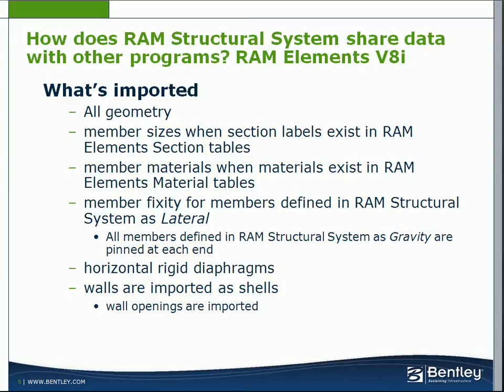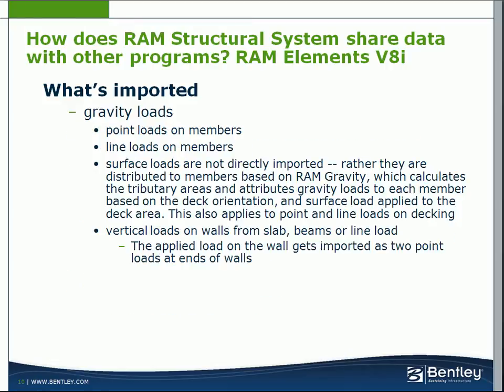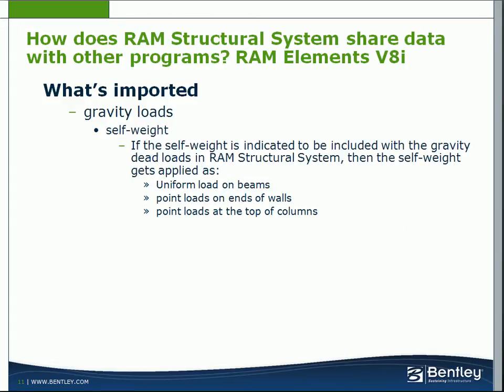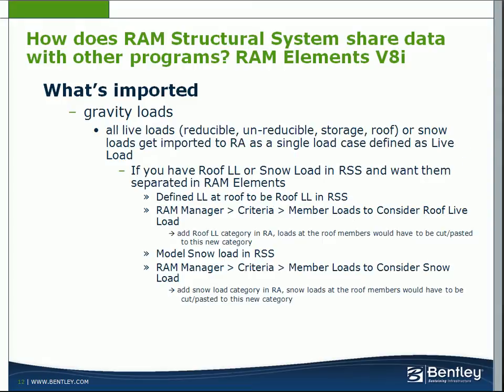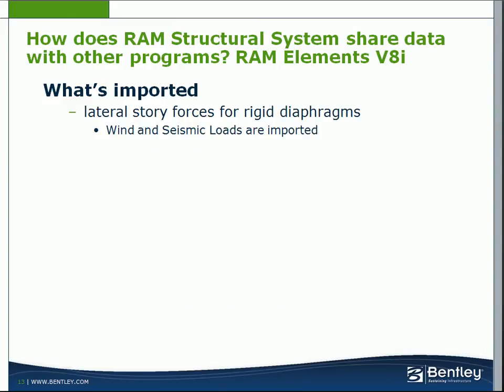When importing, member sizes, materials, and fixities all come over, as well as your rigid floor diaphragms and walls. The gravity loads, whether they be point, line, or surface loads, are also imported from Structural System. Your lateral loads from RAM Frame are also imported.